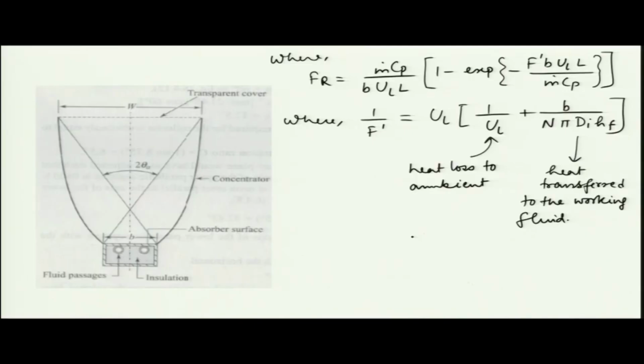So far we have looked at the two dimensional parabolic collectors. One is PTC, the parabolic trough collector, and the next one is the compound parabolic collector, which is nothing but a combination of two consecutive parabolas put together according to a certain algorithm, and that is how we get a less tracking requirement and a significant amount of concentration.